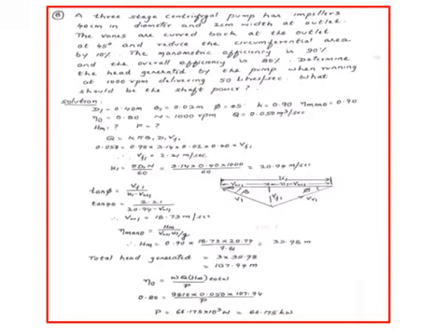So for example, if each impeller throws about 30 meters, then three times that, the total head will be 90 meters. Like this we get increased head, but the same quantity of water is flowing in each of the impellers. So you have to know this before we go and solve the problem.